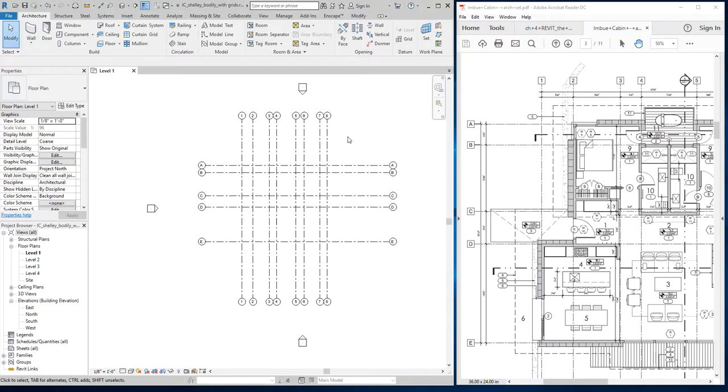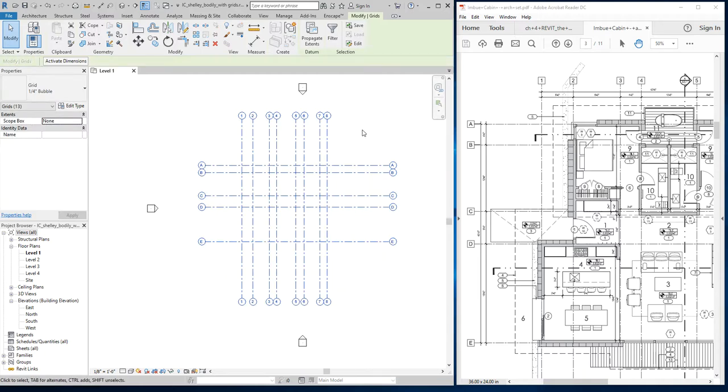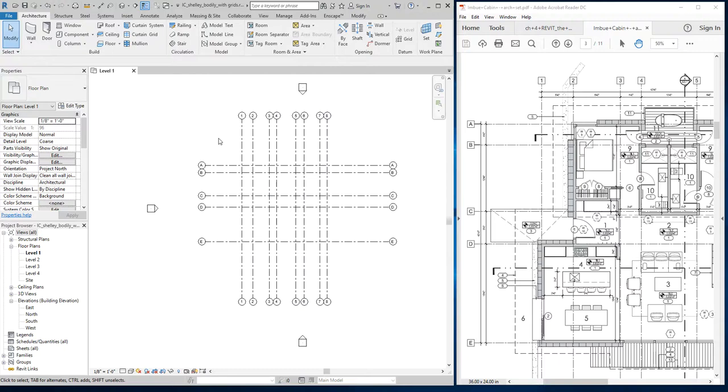Now, again, this might be one of my rule-breaking instances, where, remember I said I don't pin stuff down a lot, right? There's probably 2 things in Revit that I now will pin down for sure. When I was learning, I pinned everything down and it turned into a gigantic mess. But I will pin down a structural grid, okay? So I'm going to select them all at the same time, and I'm going to click on pin. And it pins all those down. And I will pin down AutoCAD files that I bring into Revit, so they don't move. I will definitely pin those 2 things down.